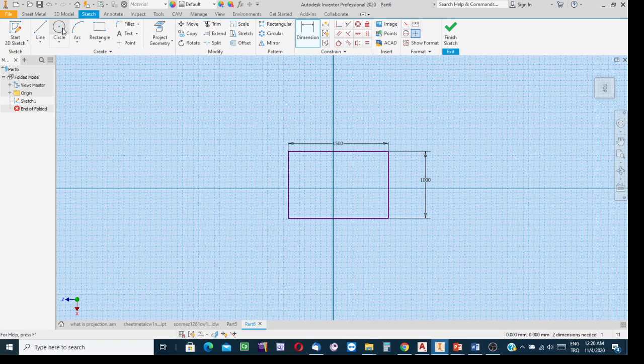And then the loft, the other cross section of the loft is circular in shape. So, although I know that there is a distance between the inlet cross section and exit cross section, to be able to locate or position the exit cross section with respect to the inlet, in the same sketch mode, create both of the boundaries, the boundary at the inlet, boundary at the exit.